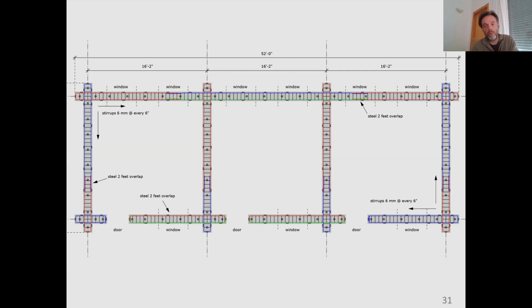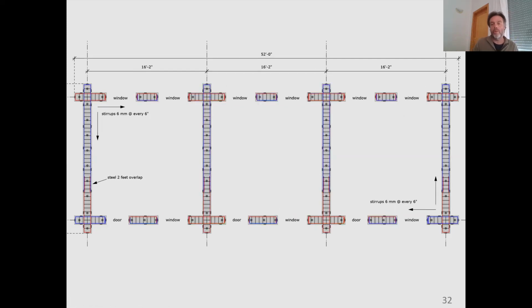At the moment that we look at the sill beam, so that's the one below the windows, then there's 3 doors here coming through. So this beam becomes semi-permanent, but still this will do quite what we want. This still adds to the box behavior. But now if we start shifting this beam 1 level up into that shear cracking zone, then all of a sudden all the windows come through. And then this is not really doing what we want anymore.